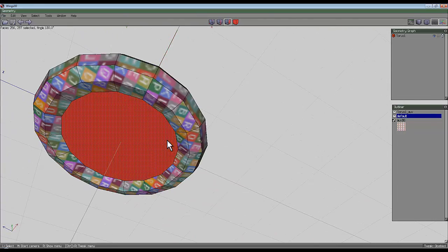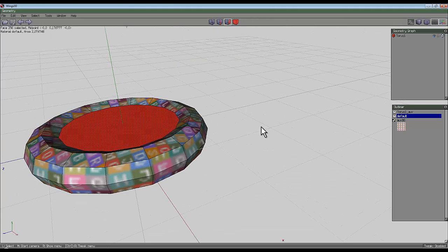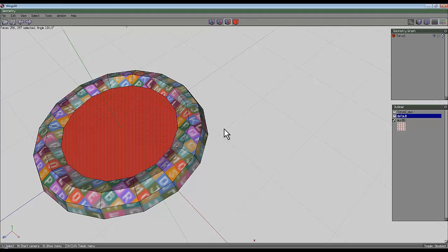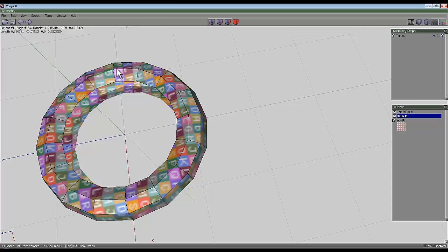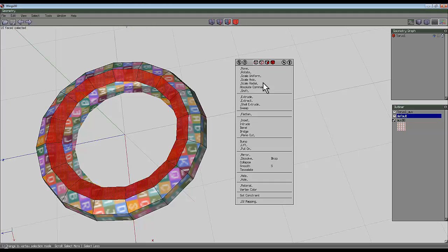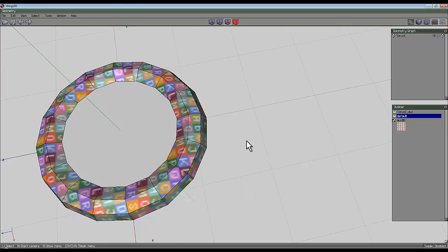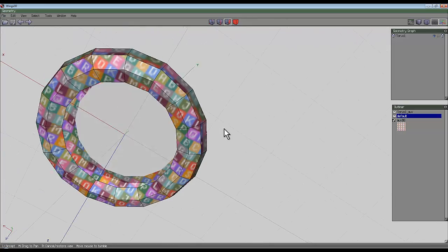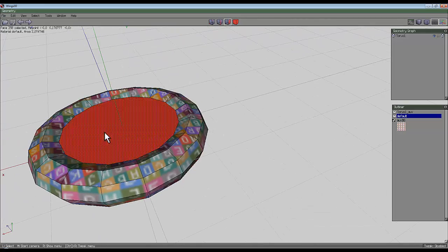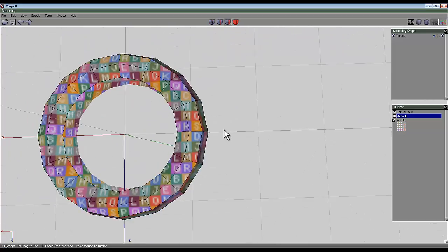So if you've done the deleting of the, I'll go back, I'll use Control Z. Okay, I'm just going back to it. If I just deleted those faces, that's the effect, and then gone hole, they would disappear. If you want a hole back, say on this side but not on the other side, go G, select those faces, and when you right click on hole, it'll bring back the geometry that's next to the faces you'd selected. So you can see we've still got the hole on this side. So that's just dealing with hole. Let's put that back in there.